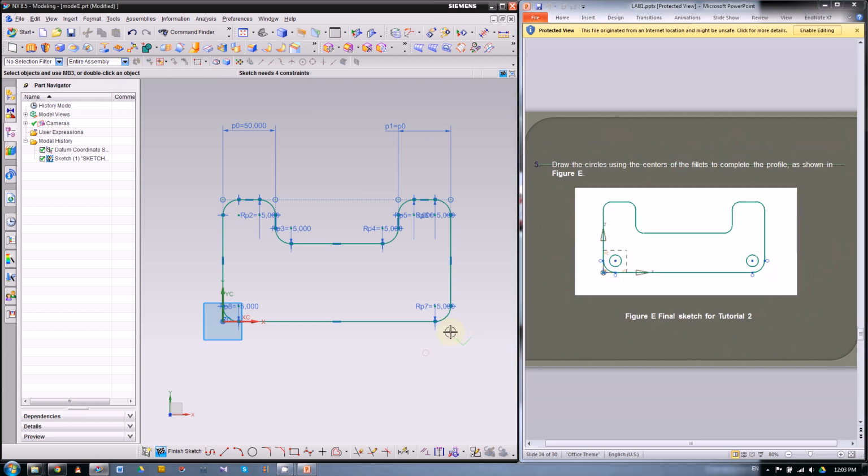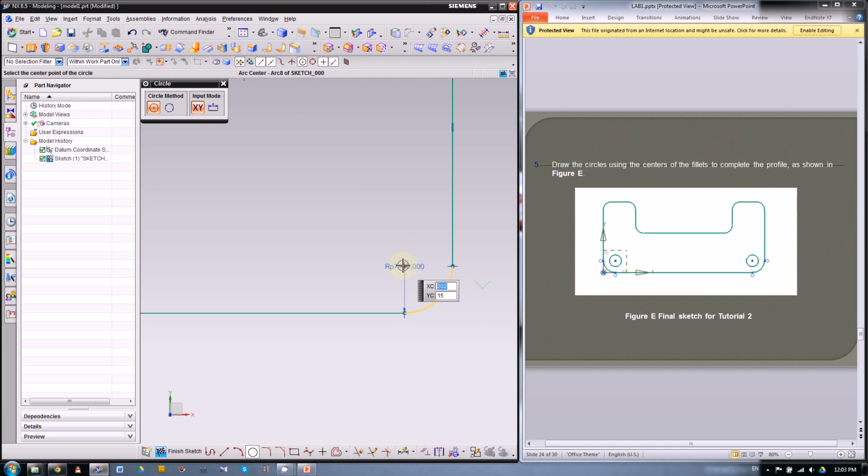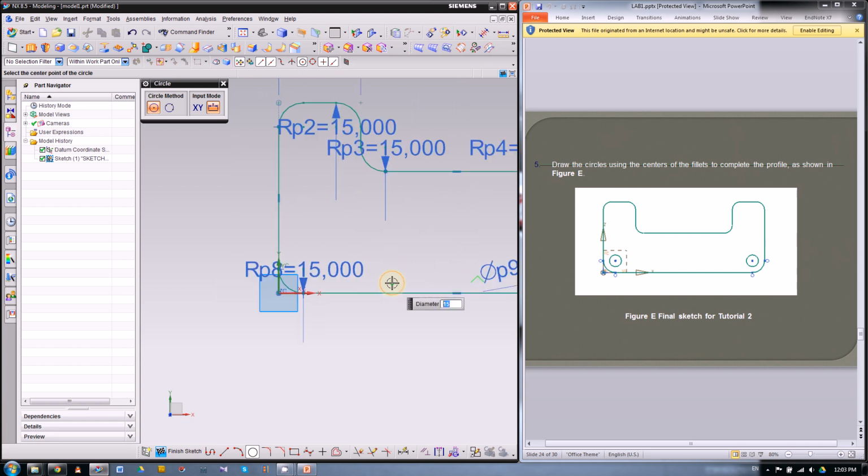So circles. This one, by default, is the center and the radius, not the diameter. So we have the snapping to the center on, and you can hover here. You'll see the icon. Click. Now you have your circle. So here you can just click and drop the circle, or you can type in your diameter. You can say 15. Okay, press enter. Then that one is done.